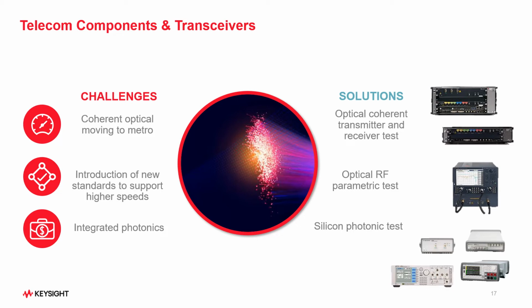The next big chunk here is with respect to the terabit receiver test. Next generation transceivers would enable telecom service providers to support 100 gig, 400 gig, 800 gig, and soon into terabit applications. To thoroughly test an optical transceiver or specifically a receiver, one should stimulate it with complex waveforms using different modulation formats and data sources.